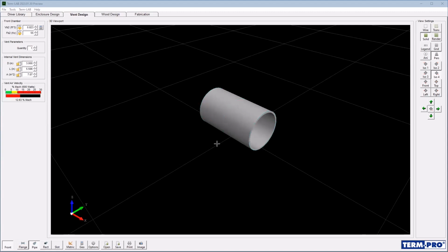Because I'll tell you this, in a vented enclosure, box volume variations of 10 or 15, 20% have very little impact on the overall performance of the system. Don't really impact the design. But changing the tuning frequency, even 1 hertz or 2 hertz, creates a huge impact on performance. So when you design the box and you build it, you really need to test the tuning frequency.